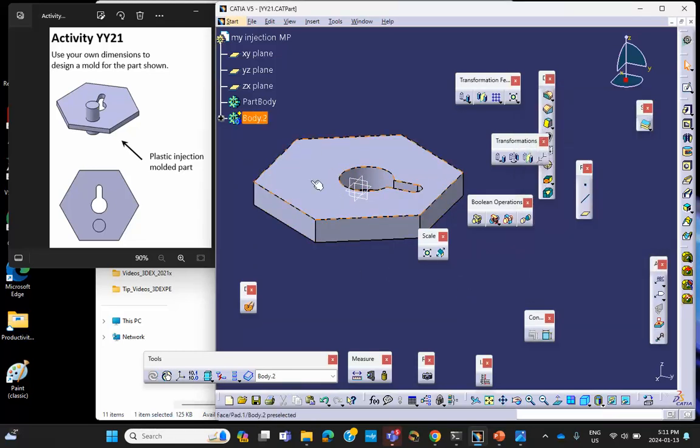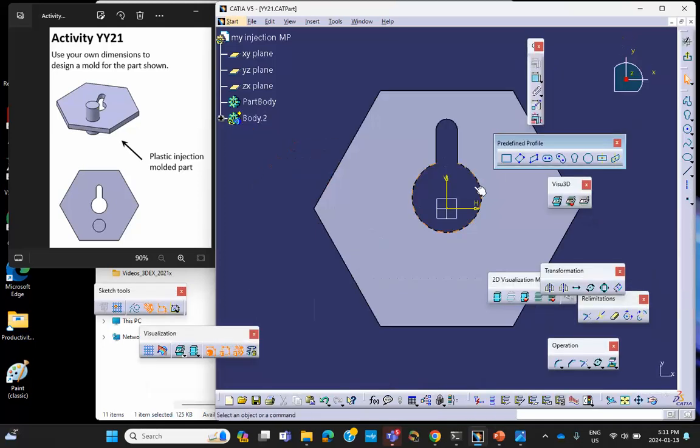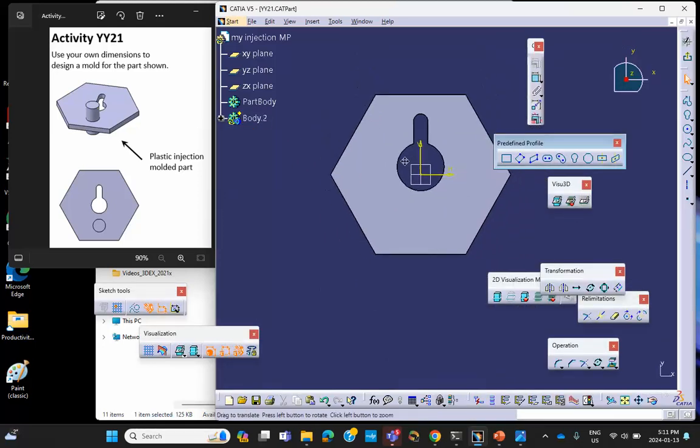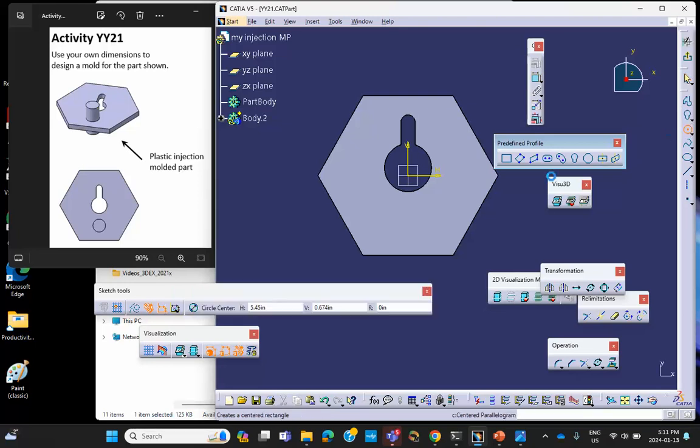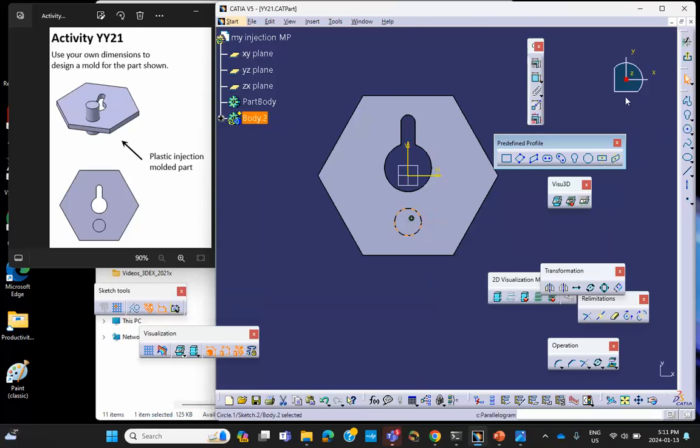All right. On that top face, I will sketch. Because if I drew a circle there, it would have been a hole here. Okay, and then probably we have to do multipad to fix the problem. That's why I drew the keyway in the sketch, and this guy I'm going to do manually here. On that face, I will sketch here, exit.